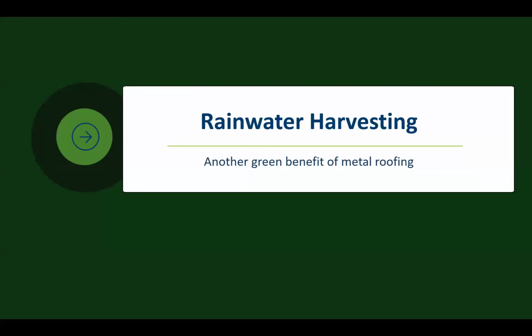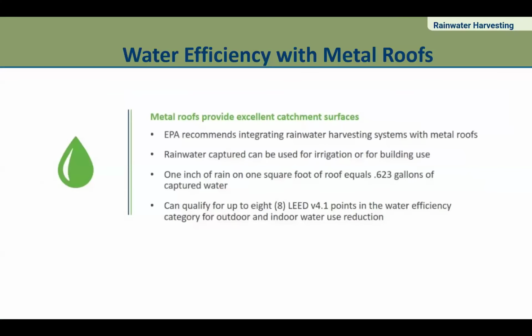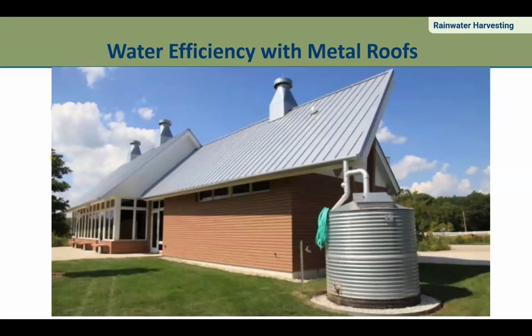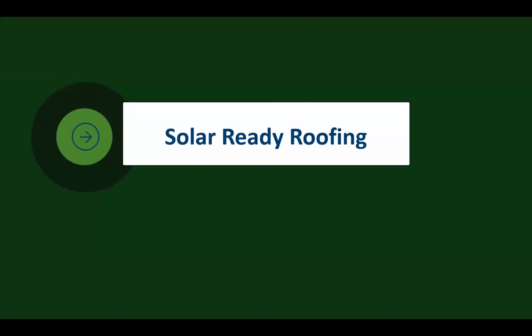A few other categories to talk about in terms of metal roofing: rainwater harvesting, where municipalities allow for it. It is a great way to collect non-potable water for gardening and so forth. PVDF finishes, which are applied almost exclusively on metal roofs, are a chemical molecule or two off of Kevlar. So it sheds water incredibly quickly and cleanly. Certainly there will be some dust and things that build up on the roof, but you won't get any of the toxic chemicals and other aggregates that you might get with, say, asphalt shingles.